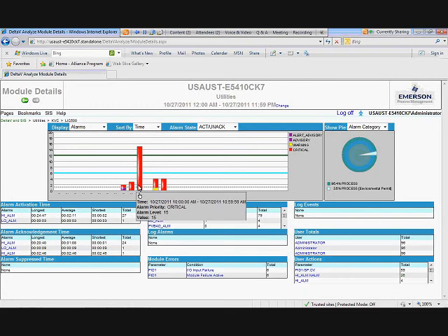And at the 10 o'clock to 11 o'clock hour, the incoming alarm rate was actually in excess of not only the acceptable level, but was actually in excess of the manageable level. These are, by default, in DeltaV Analyze, the MUA levels, although you could set those using that administrative page to a different set of names and alarm rate bands corresponding to your alarm philosophy document.